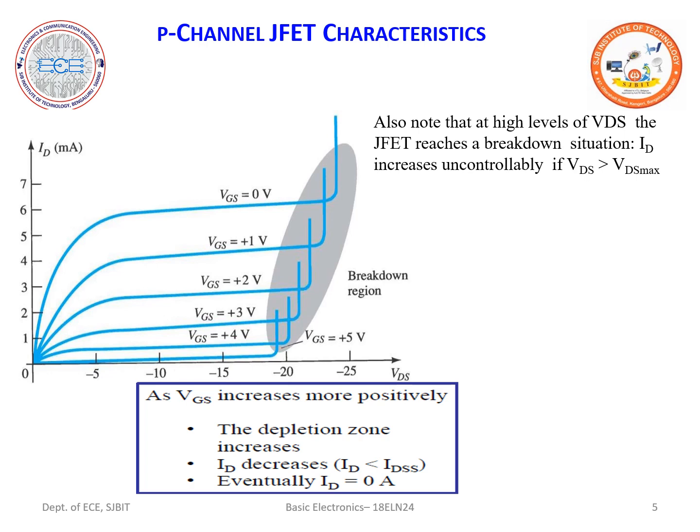When we look at the characteristic curve, where we plot VDS versus ID by keeping VGS constant, VGS is a positive voltage, and as I vary VDS, ID increases.